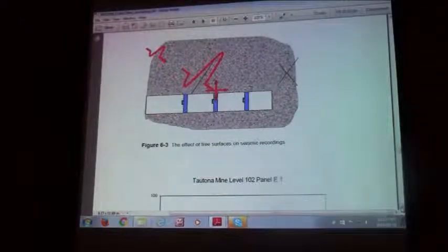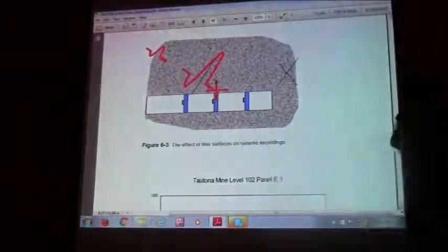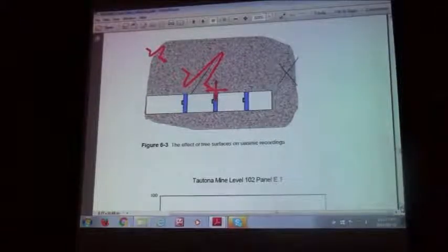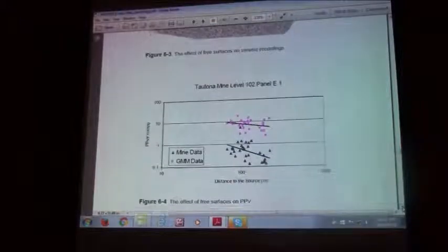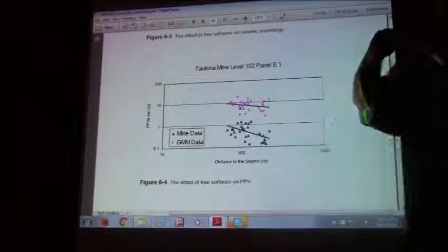What you also find, as I showed you before, around a deep excavation, you get a whole envelope of fractured rock. Now, that fractured rock has very different properties to your solid rock, and it kind of traps the energy around your excavation. These are measurements where we've had sensors on the wall of the excavation, on the roof, and 10 or 20 meters in the rock.